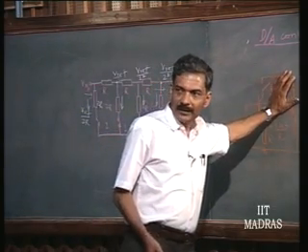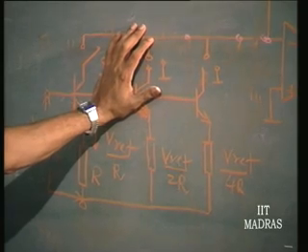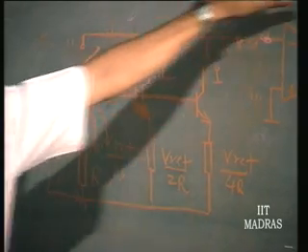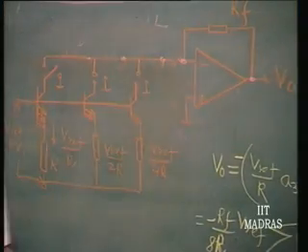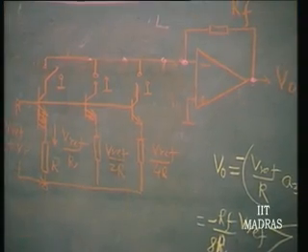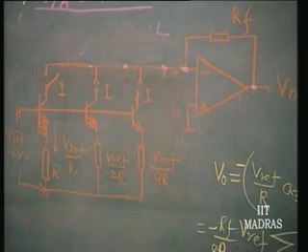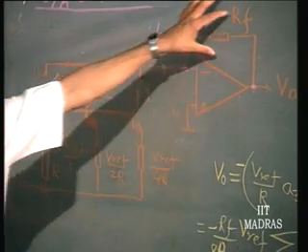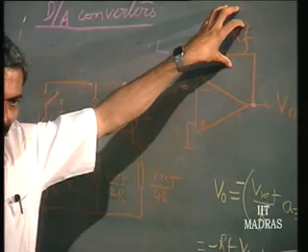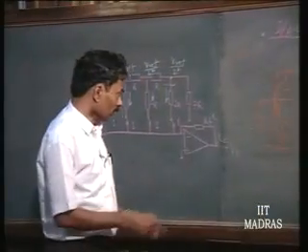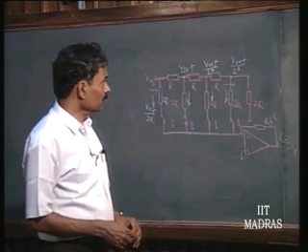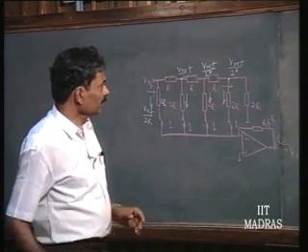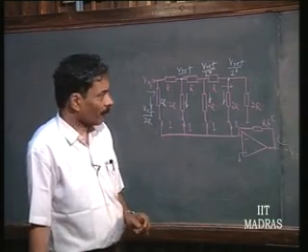The capacitor is charged to a certain voltage using a switch, and then the entire charge is transferred to the feedback or the output, and that way you can bring in more capacitors at the input and pump in the current that is necessary to charge this feedback capacitor. This kind of switched capacitor network we will discuss in the next class. Thank you.